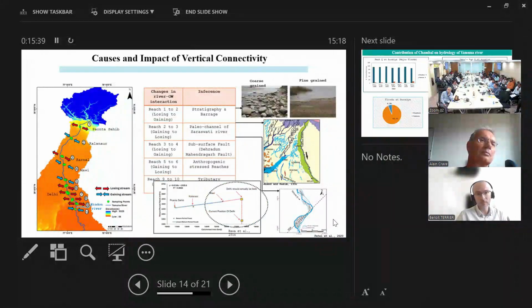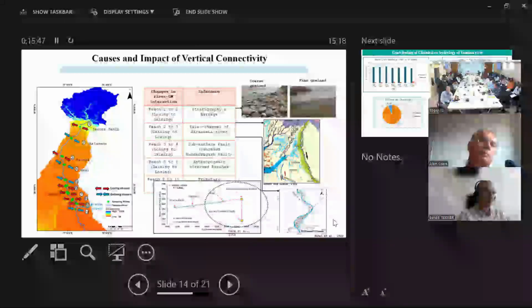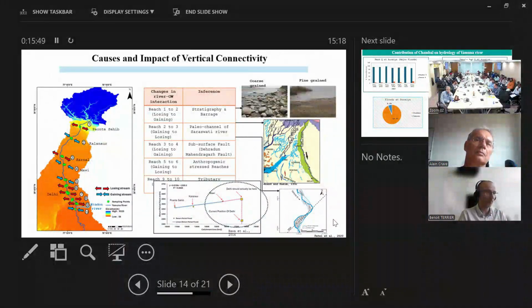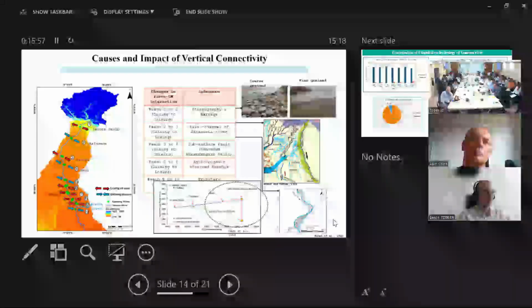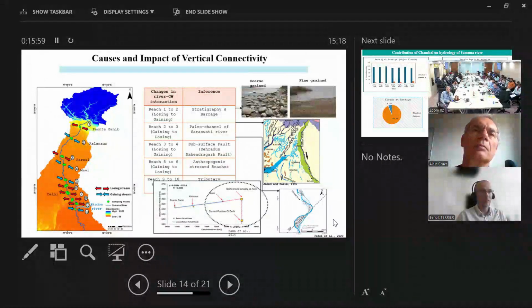So with these things, the impact is that if we plot the return period flood from upstream to downstream, these are the 3 stations upstream of the Delhi region, which show that the discharge is increasing, which is expected. But in the Delhi area, this value goes down. So we superimposed that number. This is the major gap that is coming out. So it seems that the major part is the lack of hydrological connectivity.